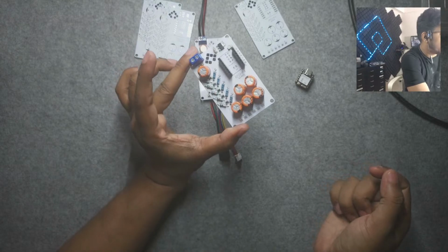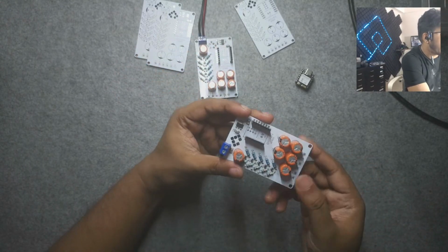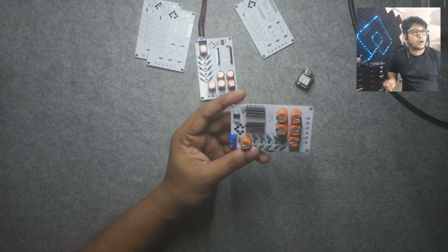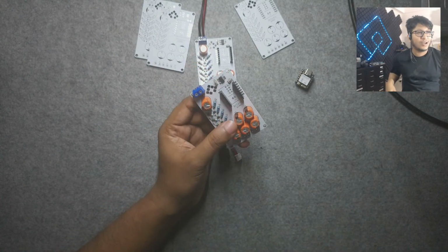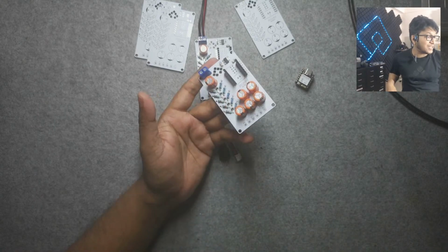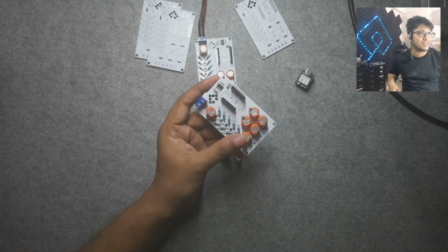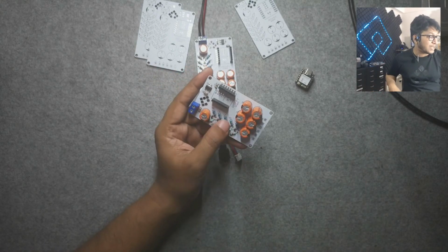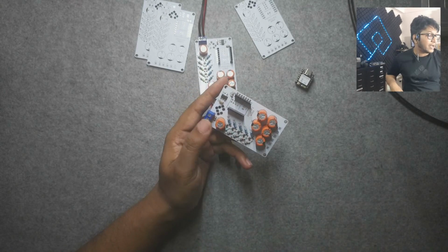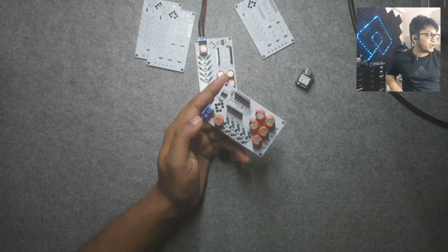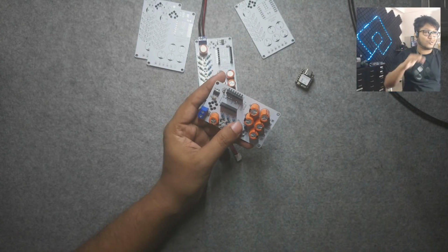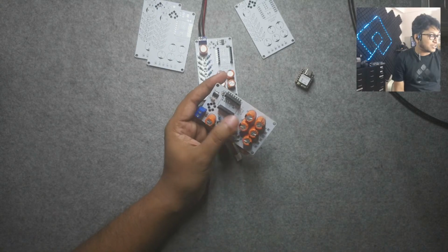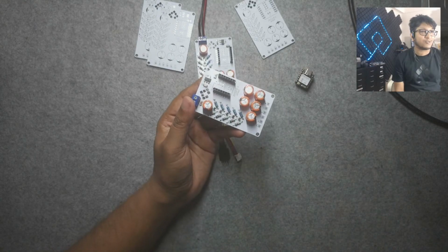I could have made it smaller if I went with surface mount resistors and surface mount capacitors. In this design, I did not go with surface mount capacitors because I was shooting for the bigger capacitors, which is a poor choice. That's the only mistake I made. I can easily go with a much smaller capacitor just to eliminate the flicker. I do not need bulk capacitors, these big charge holding capacitors. That actually does a disservice with the PWM.